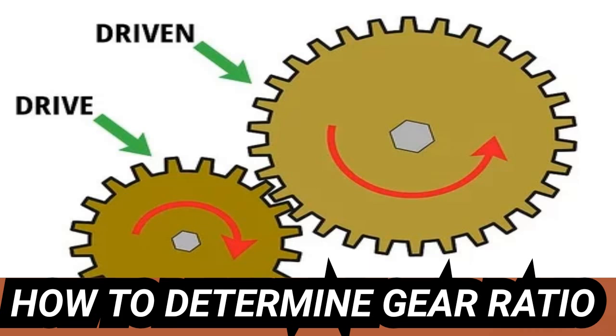6. Let's say for example purposes that the 2-gear train described above is now driven by a small 7-toothed gear. In this case, the 30-toothed gear remains the driven gear and the 20-toothed gear, which was the driver before, is now an idler gear. 2. Divide the teeth numbers of the drive and driven gears. The important thing to remember when dealing with gear trains with more than 2 gears is that only the driver and driven gears, usually the first and last ones, matter.